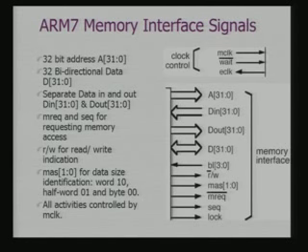Now a very obvious thing would be that if you are just putting in a ROM, a non-volatile storage where you don't need to write, you may connect it directly onto the data in bus, and if you are connecting a RAM, that would typically be connected to the bidirectional bus.